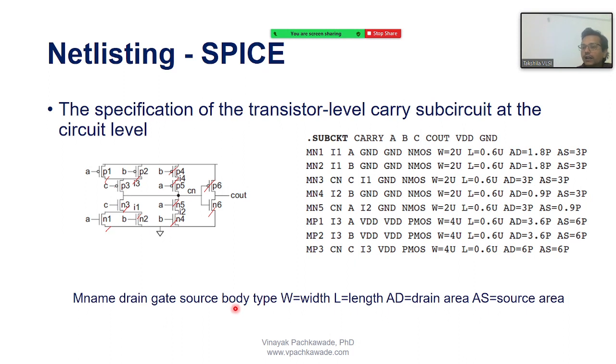So remember, in Verilog code we did not talk about the body. Okay, where is the body of these transistors and where is it connected? Can you recall that? Because this is now important for you to understand, even for the layout. So I have explained to you that this is an NMOS. So this is drain, gate and the source, and the body is connected to the source, right? So you see now there is a syntax here, drain, gate, source and body.